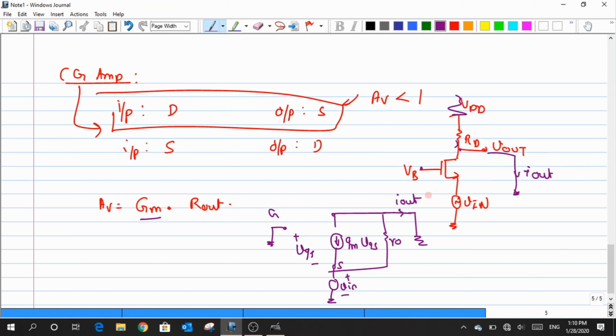So now what is the relation that I have for this capital Gm? One can even expand the value of VGS as VG minus VS, and we know that the value of VG is basically 0 just because it has been grounded. Okay, and what is connected to my source potential is just the value of Vin. So I just fix this Vin. So in the place of VGS I have minus Vin, right? So the current that I can expect out of this is nothing but this current plus this current.